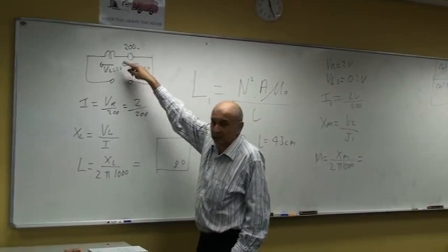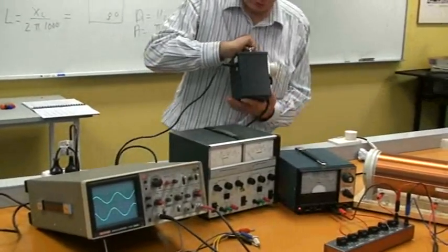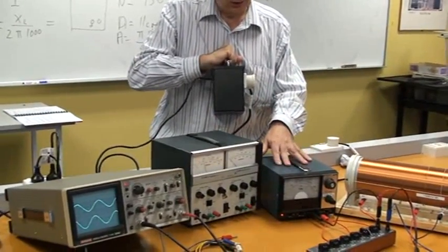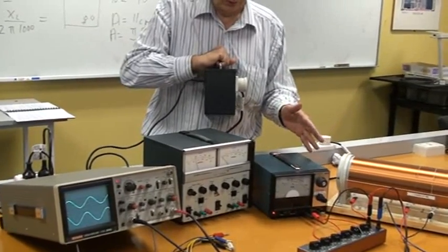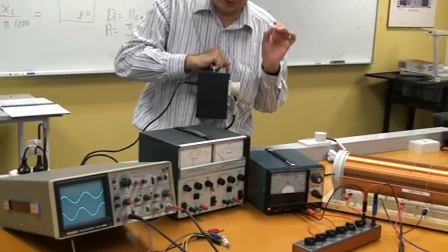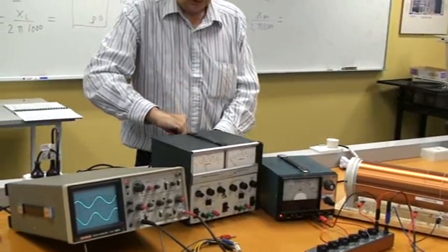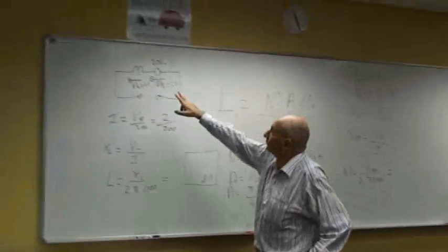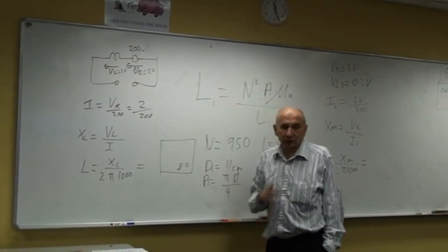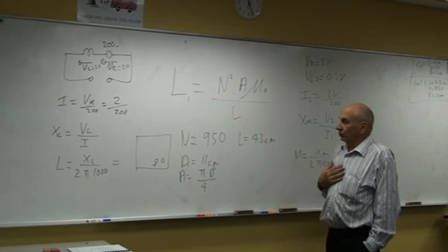That would short out the resistance. So I got around that problem by using this thing. This is called an isolation transformer. And what that did was isolate the signal generator from ground. So even though it says earth on there, in fact in this particular case it's not earth. Just for this one lab, that point is not the earth point. And I've chosen to earth a different point in the experiment. I've chosen to earth this one here. That's a sort of a small point. But you should put that in your logbook. It's an important result. Well, it's an important thing you should have learned.